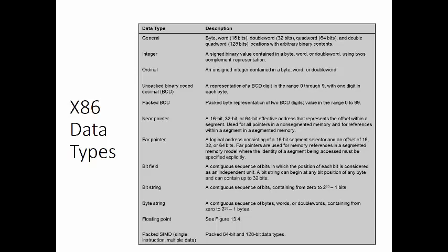To allow maximum flexibility in data structures and efficient memory utilization, these words, which are the 16-bit ones, need not be aligned at even number addresses, and so there are mechanisms for dealing with them when they're not completely aligned. Likewise, double words, which are the 32-bit ones, don't necessarily need to be aligned to addresses evenly divisible by 4, and so on. The processor basically can convert the request for misaligned values into a sequence of requests for the bus transfer.